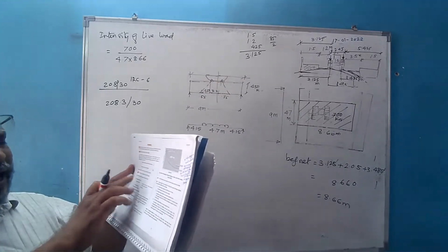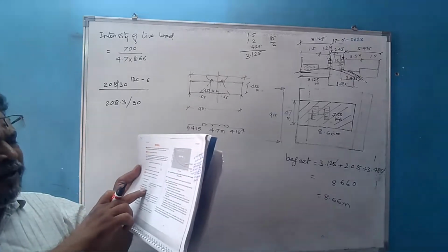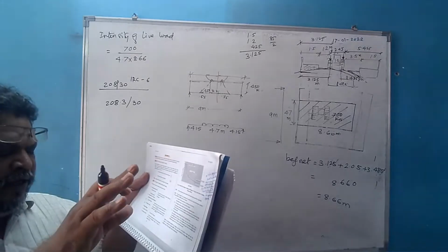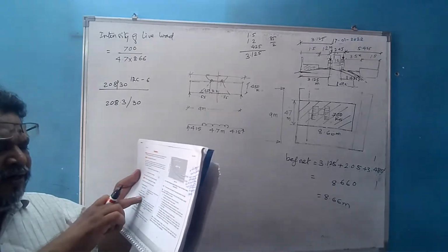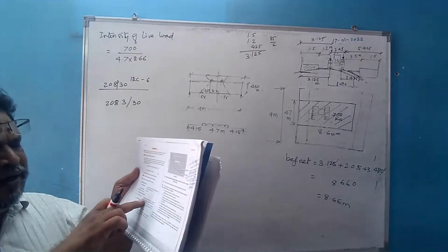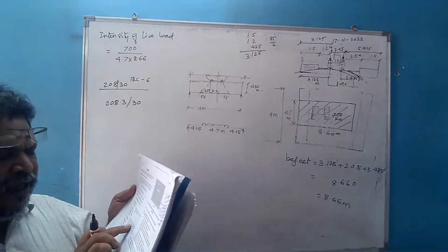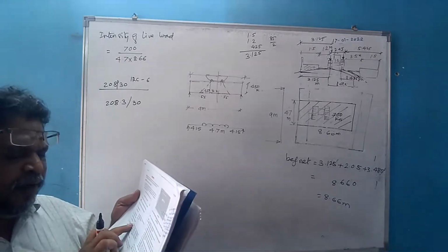For span less than 9 meter, we will not look at that. For span 9 meter or more, it is applicable for us. Reinforced concrete bridge, so it is equally applicable for pre-stressed concrete bridge. Tracked end wheel, ours is a tracked vehicle. 10% up to a span of 40 meter. From 9 meter to 40 meter, we have to increase it by 10%.